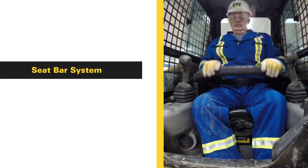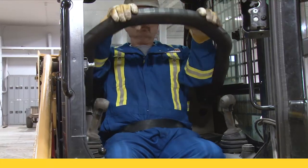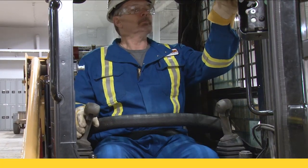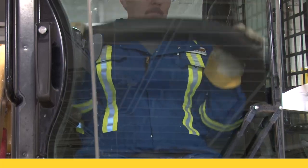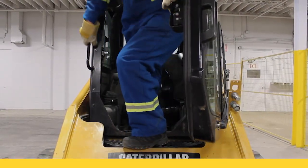Seat bar system. Along with the seat belt, the seat bar keeps the operator in the seat. The seat bar system has a pivoting bar with armrests that the operator controls. When the seat bar is up, the seat bar system will lock the lift and tilt control pedals or levers in neutral. If the seat bar does not work in this manner, do not operate and alert your supervisor immediately.